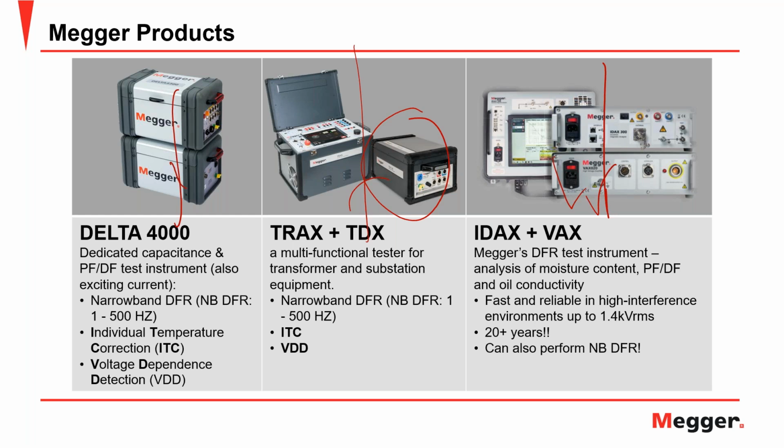And IDAX has the beauty of being a system that has been for such a long time in the market, with an excellent reputation, and being used by most manufacturers of power transformers. And you can see also that it has the ability of using the amplifier, so you can use a full spectrum DFR up to 1.4 kilovolts RMS.